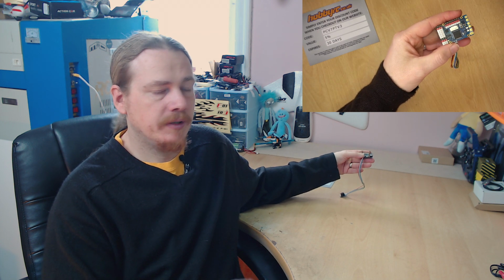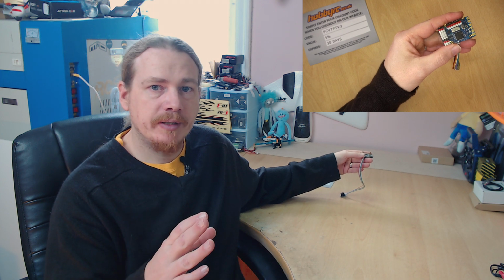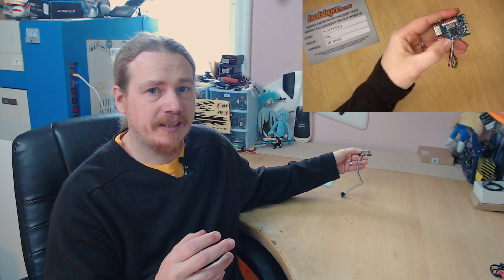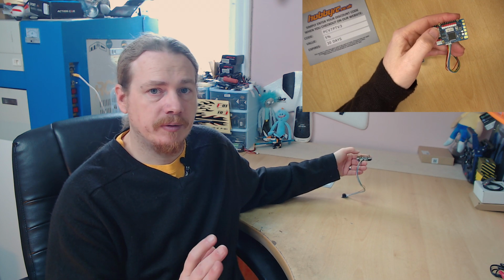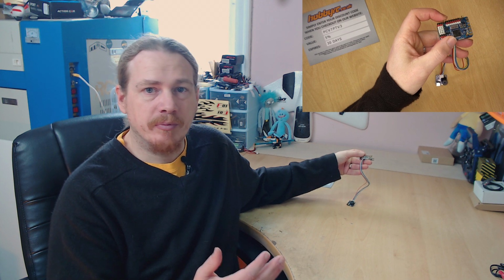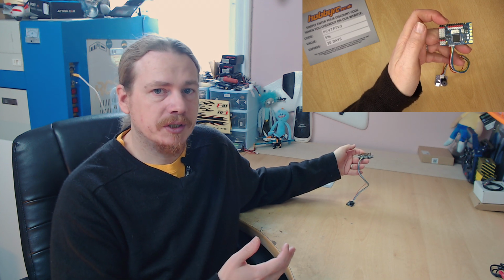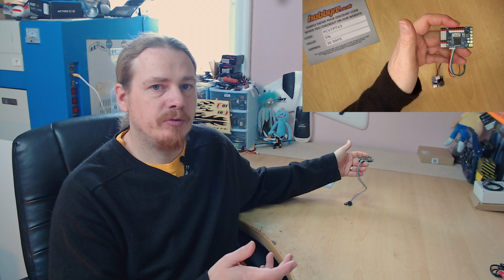As you see, I've already done that, but I have tested this flight controller prior. So this part of the video I would recommend doing as soon as you take it out of the packet. Don't even solder anything on whatsoever. That way, if there is a problem with the board, you can quite happily send this back for a replacement, and there's no arguments. You've not done any soldering to it whatsoever, so there is a genuine board fault.